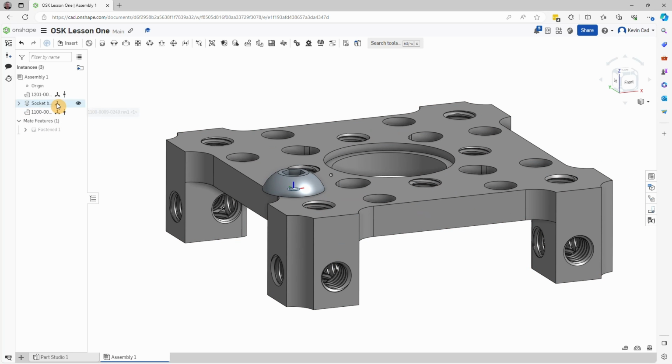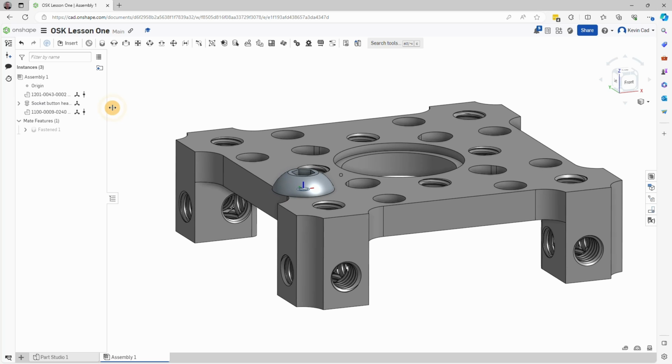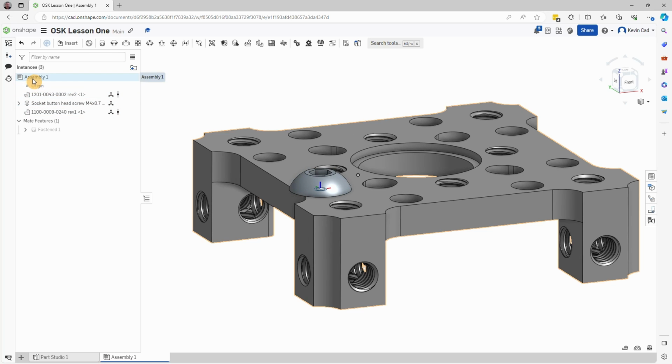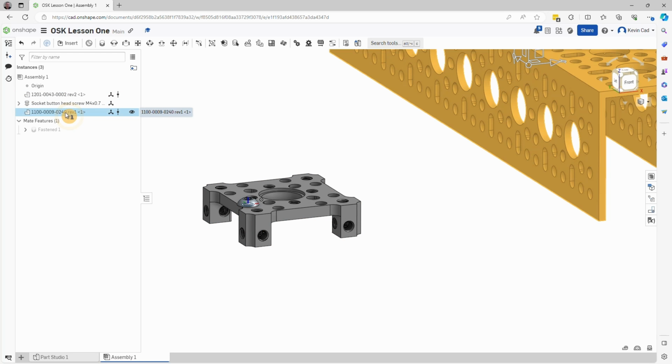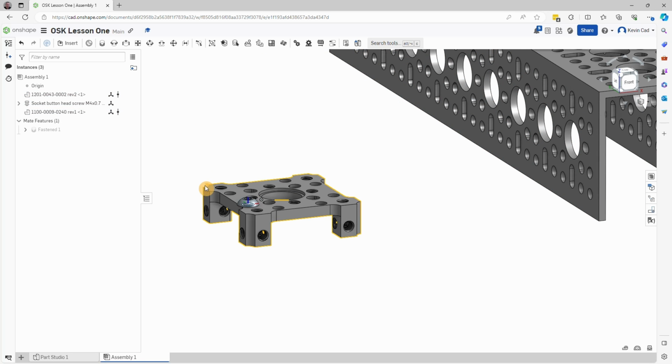So we have, look at the assembly here. So what do we have? We have parts. This is a list of the parts that are available. And if I scroll out, and as I hover over each one, you can see it highlights it a little bit. And actually, if I click on them, they will highlight. So there's that big U channel. There's a button head screw. And here's this part. Notice my mouse, it's got that little 3 next to it. That's telling me I have selected 3 parts out here. Okay. Remember the notion of clicking on nothing? I'm going to click once with my left mouse button, and that unselects all of those things.